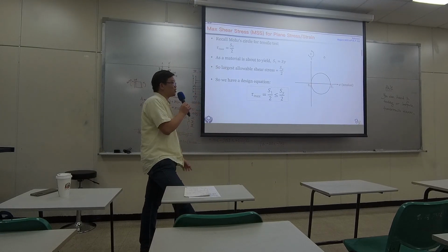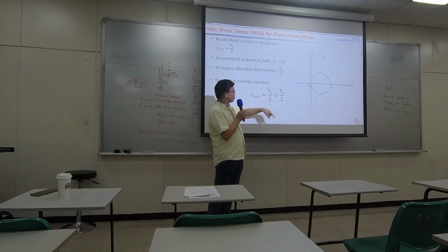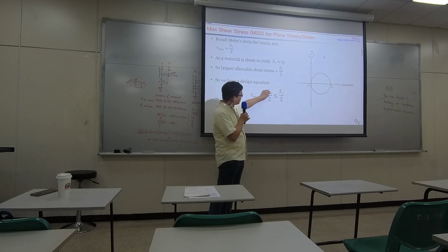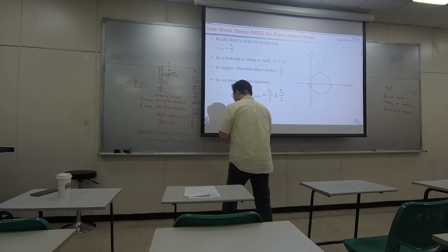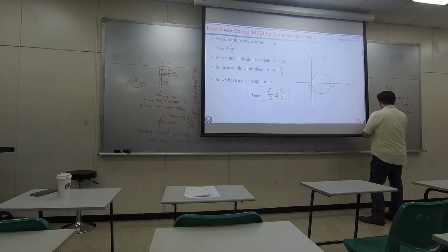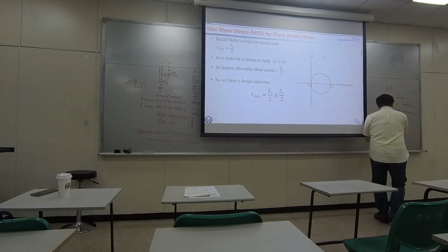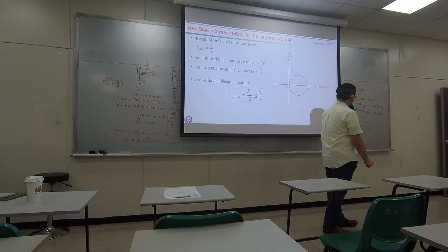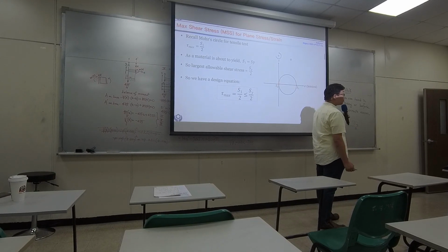That's the first equation, the design equation. So later on, if you figure out the stress equals, for example, MC over I, you can just plug in. So MC over I over 2 must be smaller than your yield strength over 2. Okay, so you could already have some equation like this: MC over I over 2 smaller than yield strength over 2, right? Of course, those 2's cancel out. You have MC over I smaller than your yield strength.